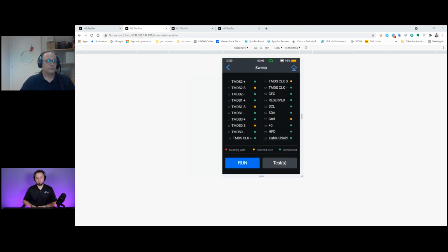It will protect, but at the same time, it will inject it directly to the data lines of the video. So actually what you're doing is that instead of providing better shielding, you're injecting the noise directly to the data lines, and you will receive a video drop. You will see a problem. So this is very important to understand.